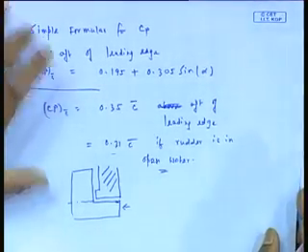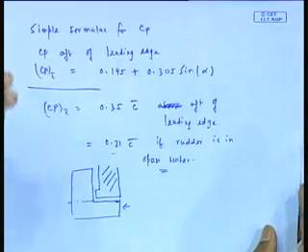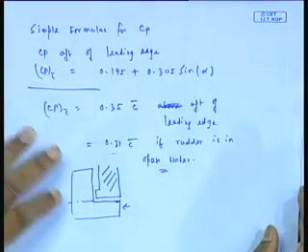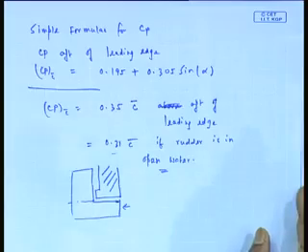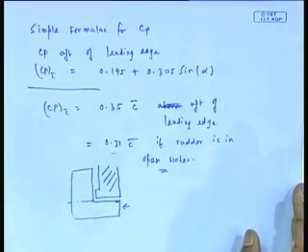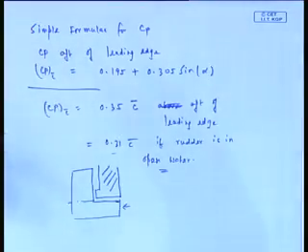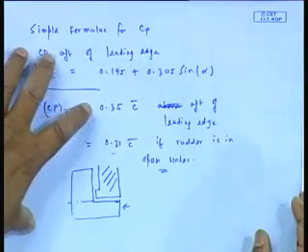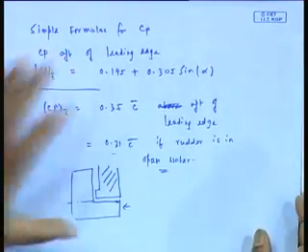Depending on the problem, suppose I have to do an estimate very quickly. Say somebody has given you a rudder, and you are a designer, you have to design the rudder stock, how thick it will be. You can very quickly estimate the bending stress and the stresses coming on that based on these formulas. If you want more sophistication, obviously you go for the CL CD formula, the better formula which uses bigger expressions. So it is a very simple thing, really. When you talk of rudder, I wanted to mention the possible formulas available. Remember, all of them are ultimately formulas to aid a designer.